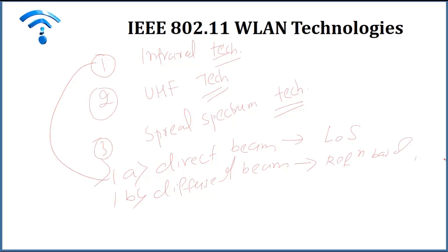If these kinds of things are there, then obviously I will not use this kind of short range technology. In indoors, it can be limited by solid objects like doors, walls, merchandise, and racking. In addition, the lighting environment will also affect your signal quality. There will be ambient light, reflections, and many frequencies in your room. The fluorescent light is a major source that will create a problem. So that's why infrared will not be considered for use as much.